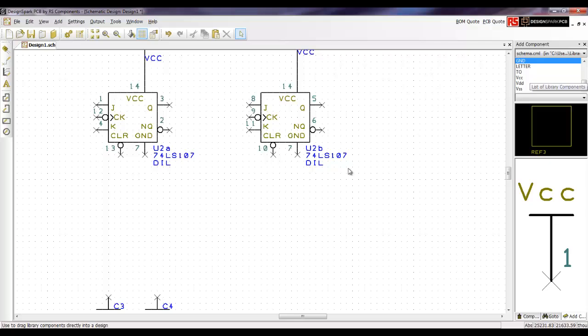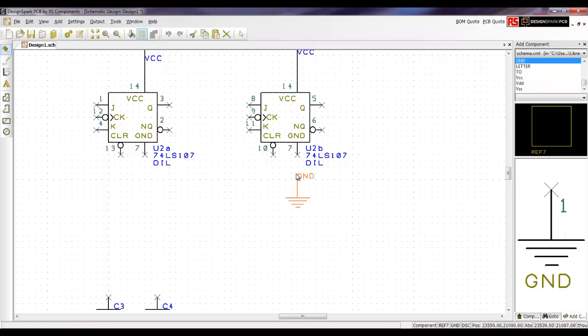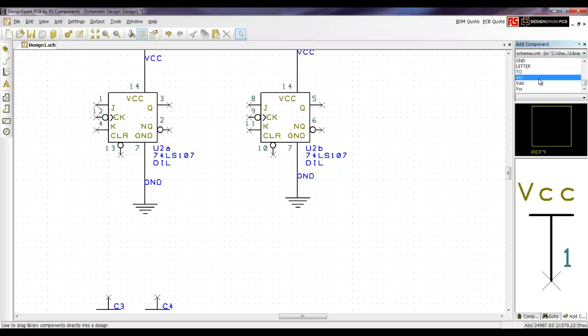I'm going to continue to connect, doing some more connections using more schemas. This is a clear. I'm going to use a VCC schema to tie it high. The clear is active low, so if I tie it high, it will not be activated.